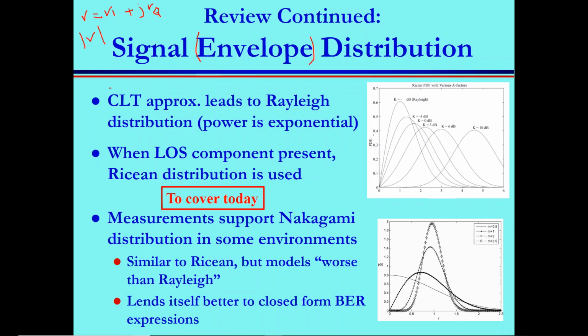we studied its distribution, the probability distribution function. Ri, by assumption, by nature, has a normal Gaussian distribution. Why is that? Because we have a large number of random signals reaching the receiver at the same time.